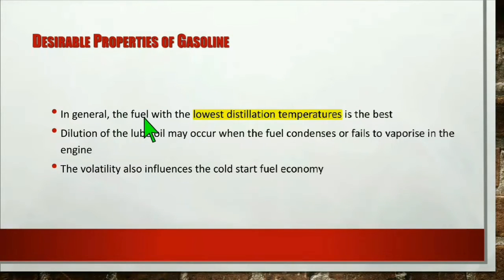In general, the fuel with the lowest distillation temperatures is the best. Dilution of the lube oil may occur when the fuel condenses or fails to vaporize in the engine. The volatility also influences the cold start fuel economy.